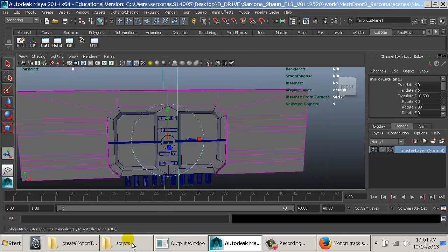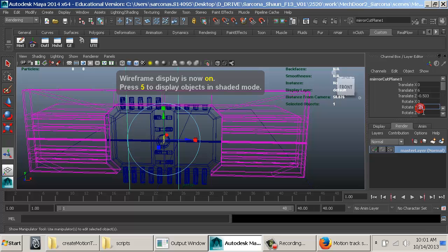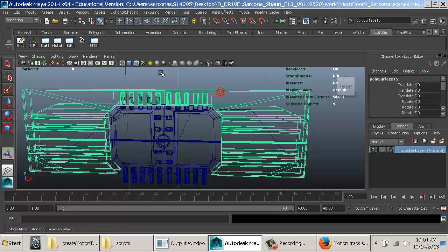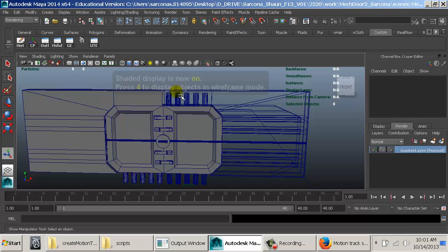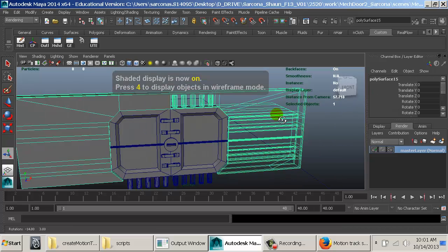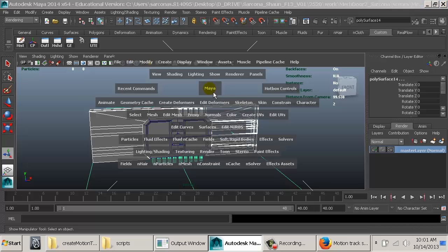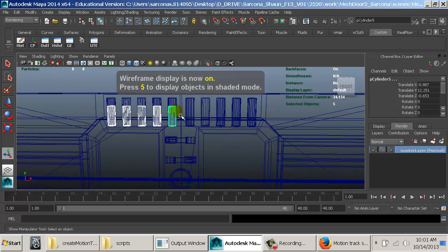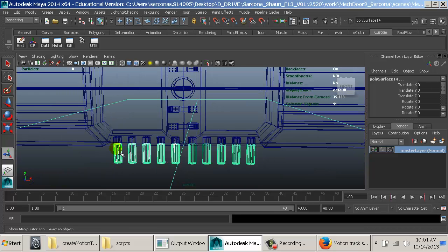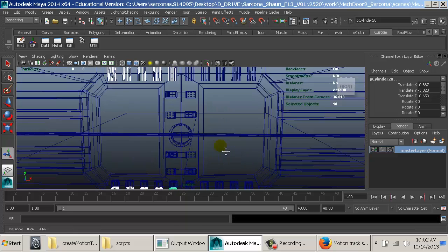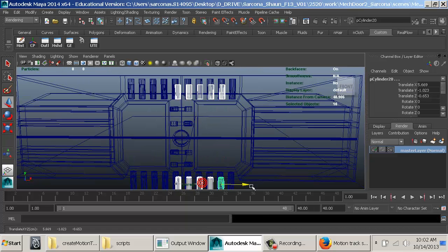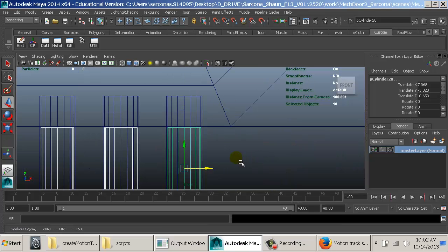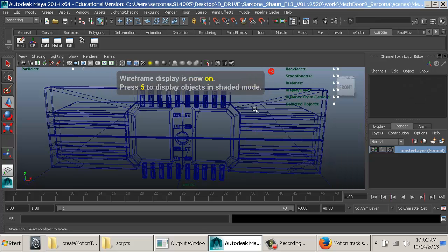Okay, so Mesh, Mirror Cut. I did the wrong side, so I changed my Y to 270, and it does the right side. Delete history, delete that. Sometimes when you mirror, you just lose your shaders. So just reassign Lambert 1, and you'll get your stuff back. All right. So I do need to have these little pins copied over as well. So I'm just going to duplicate, and I can just move them over. There we go.